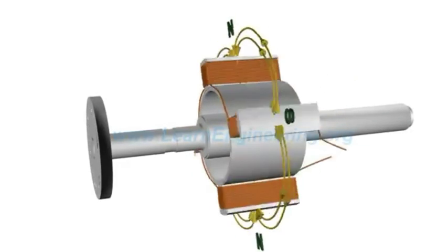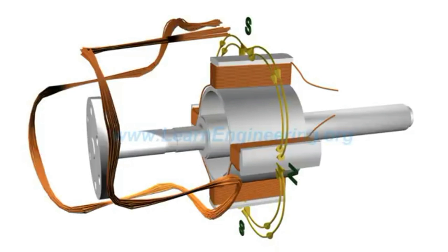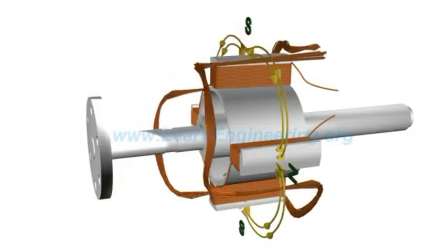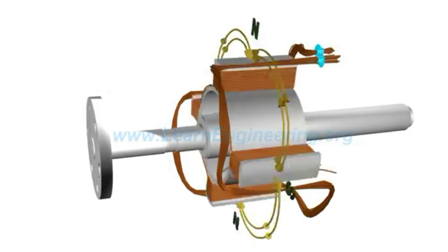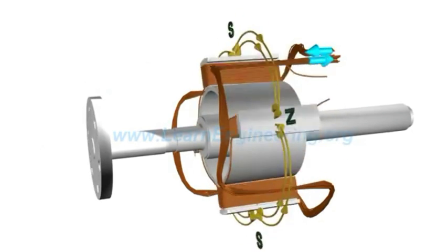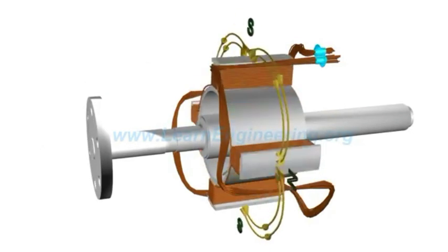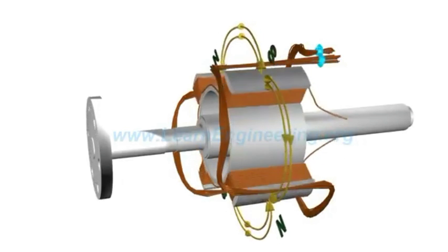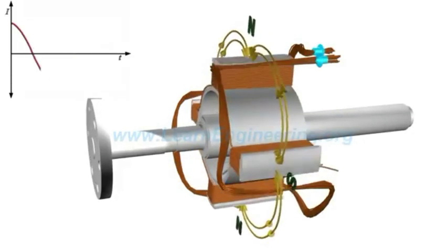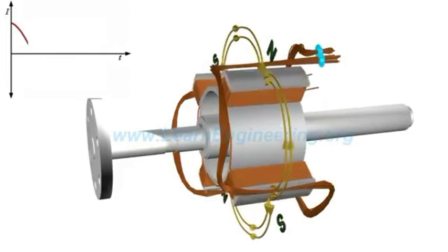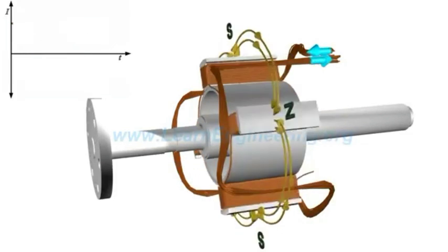Such revolving magnetic flux now intersects armature coils, which is fitted around the rotor. This will generate an alternating EMF across the winding. Here is a slowed-down version of rotor-stator interaction. For this 4-pole system, when the rotor turns half revolution, induced EMF takes 1 complete cycle.